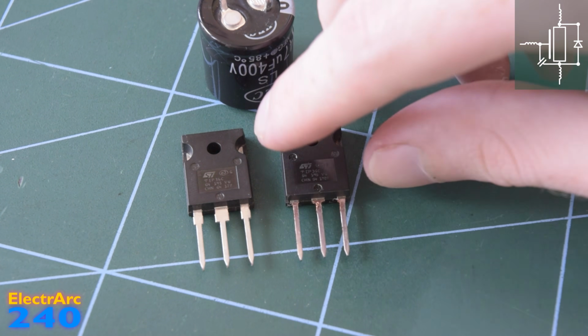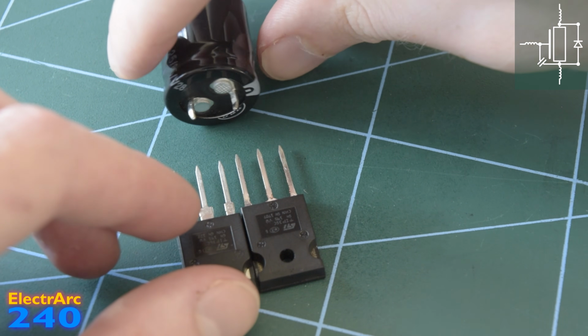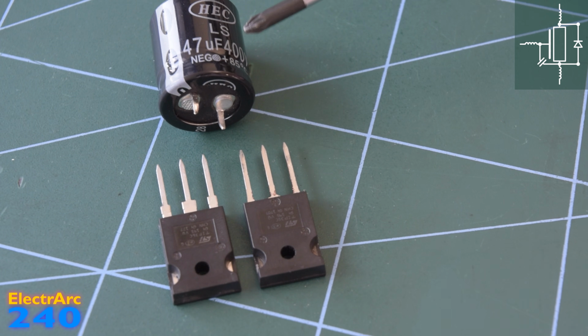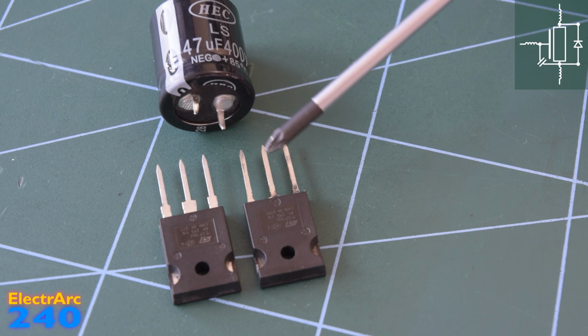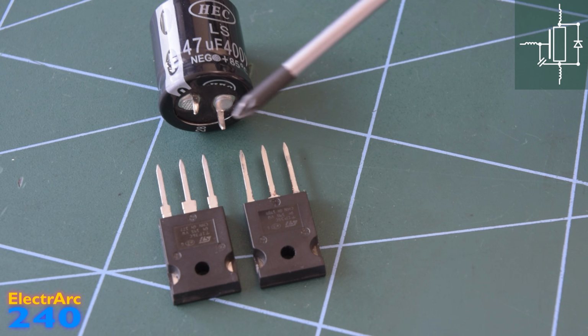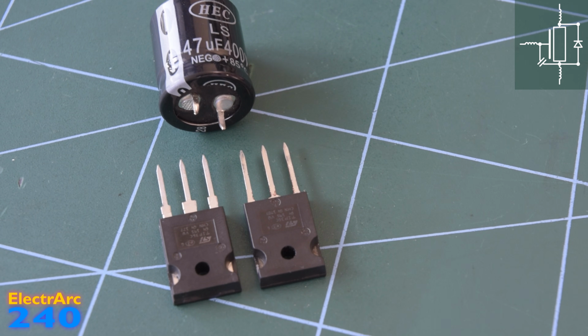What I'll do here is arrange these MOSFETs and this capacitor in a way that would be fairly typical for a half-bridge. The 2 MOSFETs would be mounted on a heatsink, and this capacitor would be on a PCB next to them. We can approximate the loop inductance by looking at the loop area. That's the area marked out by the path of current from the capacitor through both MOSFETs and back to the capacitor. So you can see it looks fairly small in this case, but wait until you see a surface mount equivalent.